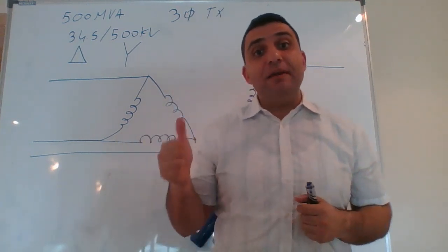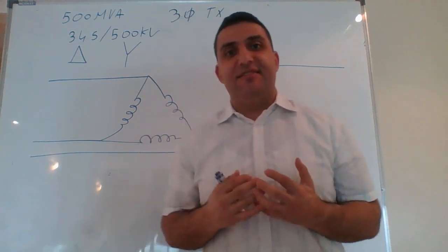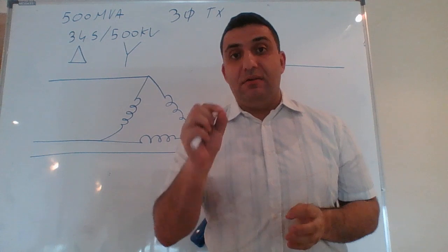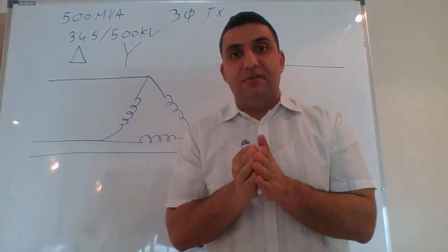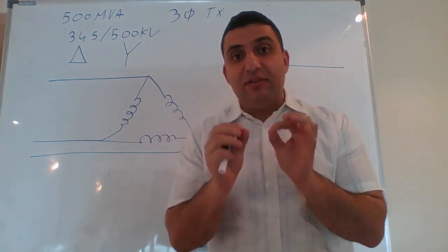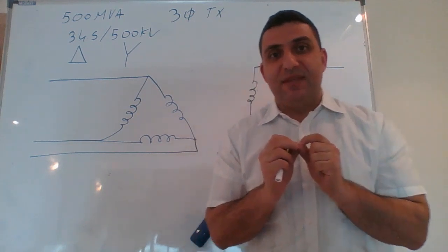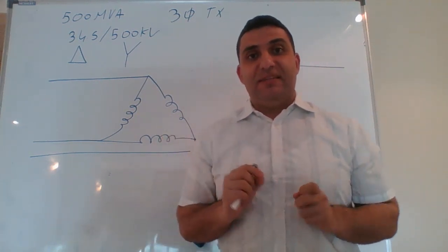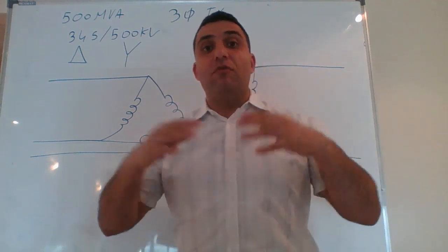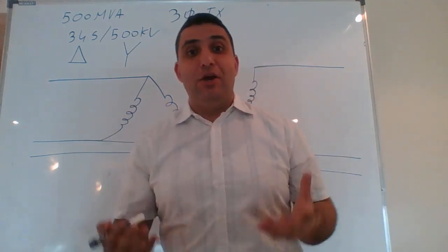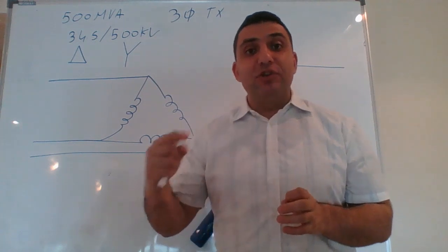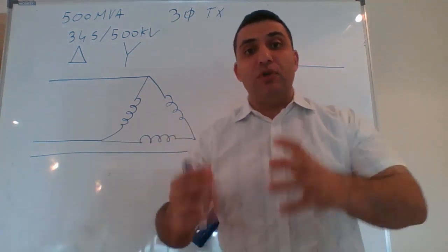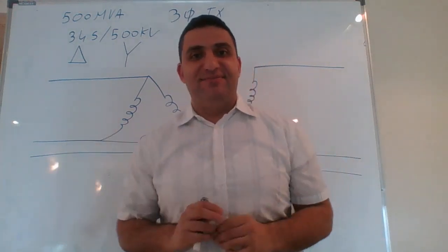Also, we have one more advantage as engineers to resolve this issue. We noticed this, which is very important, so be careful and pay attention. Engineers noticed that the inrush current is made almost entirely of harmonics, while the normal fault current is made almost purely of the fundamental frequency.